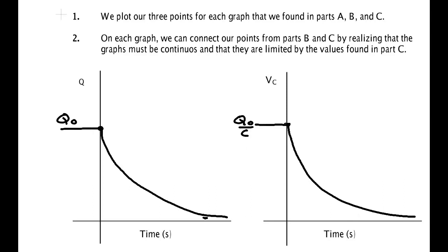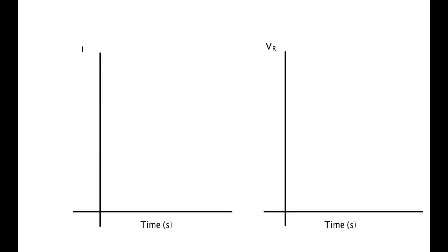So there was voltage on the capacitor before the switch was closed. There was charge on the plates. We plugged it in. We closed the switch, and it exponentially decayed. In terms of the current, there was no current. All of a sudden the current jumped up, and it jumped up to whatever that voltage was, divided by the resistance, and then it went down, and the voltage jumped up.